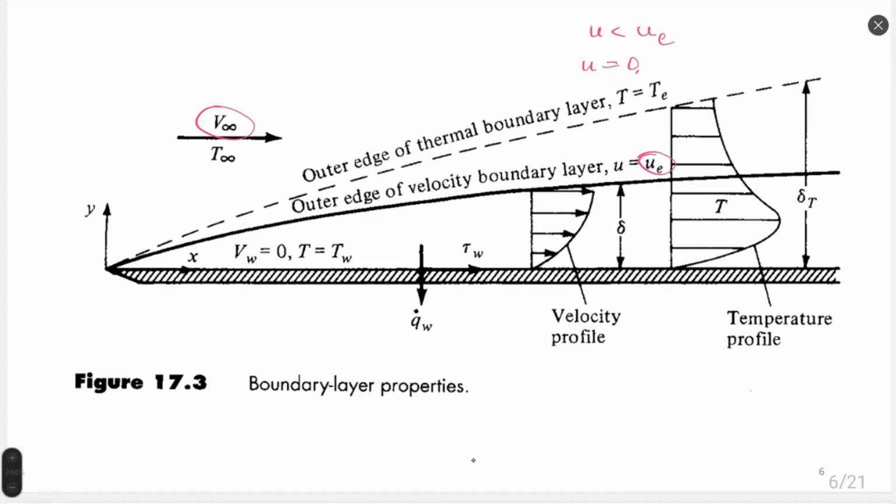Due to fluctuations, due to unsteady processes, due to presence of free turbulence inside flow, we always have variation of velocity in each particular point. So typically, once we analyze flow pattern, we can determine that when velocity reaches from 95 to 99% of external velocity, we reach the edge of boundary layer.